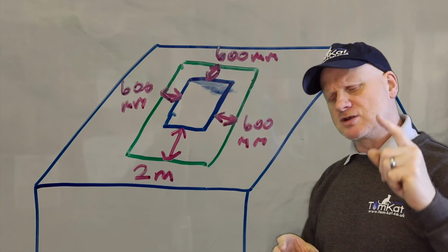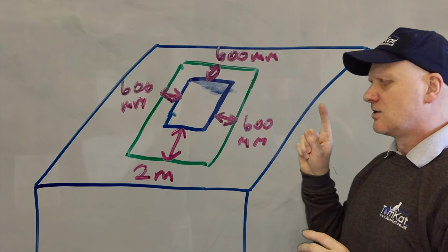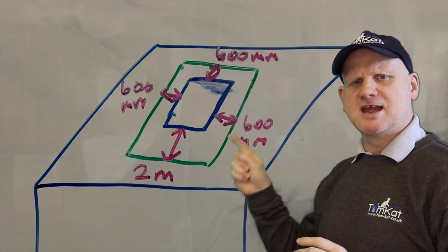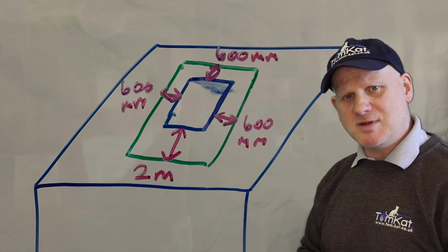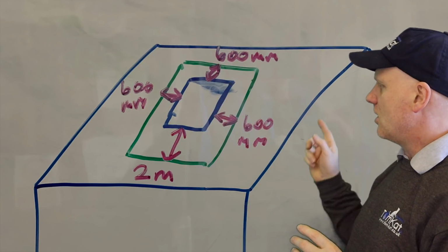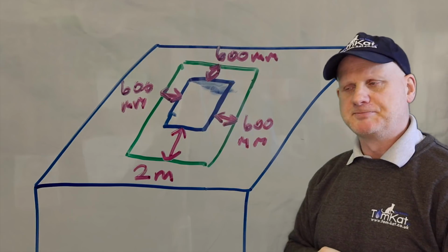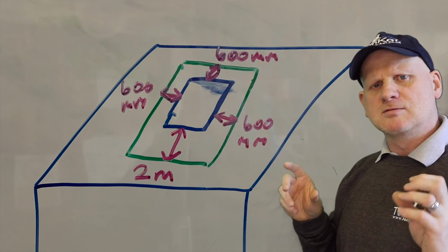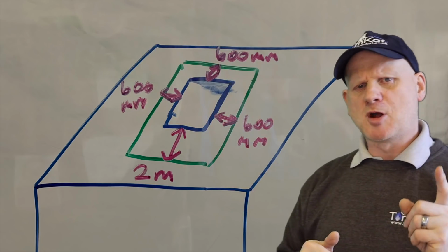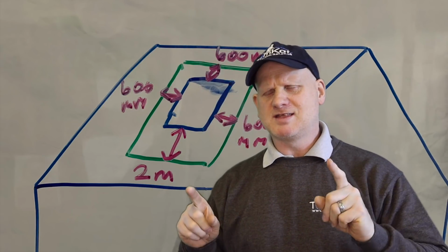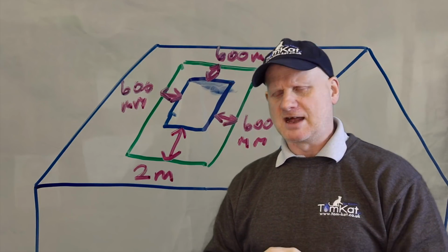And this is not just for room sealed appliances, this is for open flued as well. So you can see from the bottom of the shaded area to the bottom of the Velux window, it's 2 meters. And then all around the other area is 600mm. So Velux windows can become a problem. And they become a big problem if the Velux window is fitted after the flue has been installed. So just watch out for that one.